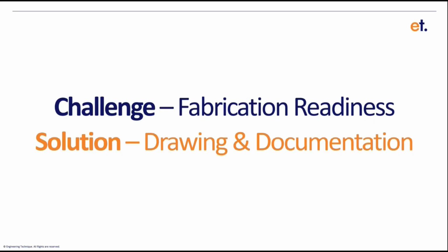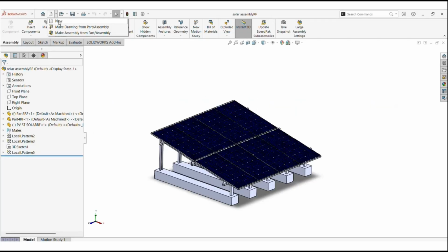To provide that, we need to create a particular drawing, a fabrication ready drawing of the model, because the fabrication team couldn't get all of the data from the model itself. They need particular views, dimensions, ballooning, and bill of material. To generate that, SolidWorks offers you drawing and documentation in it through which you can generate those drawings very easily. Let's see how it is generated.